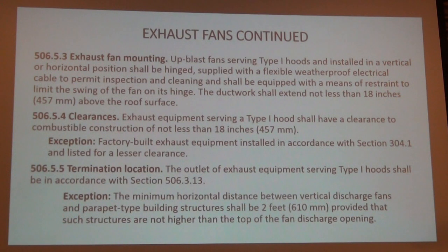Anytime you do a restaurant, you always want to open that up. It's a Limbach job, but it wasn't you guys, it was the electrician. It was Delphi's cafeteria, and I was checking for the cable jacket on the fan and the seal type for the fan. They drilled a hole through the grease duct and wired the fan. So you never know what you'll find, Mark, out there. But the Limbach got an extra for that one to fix it.